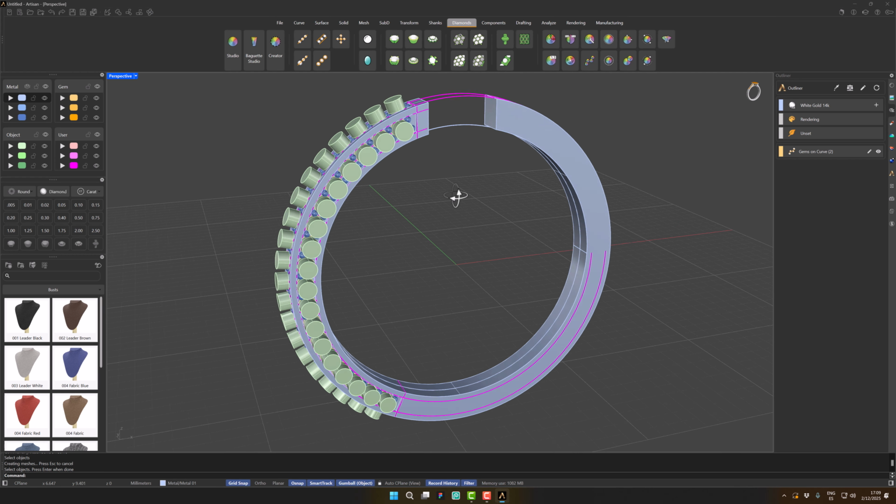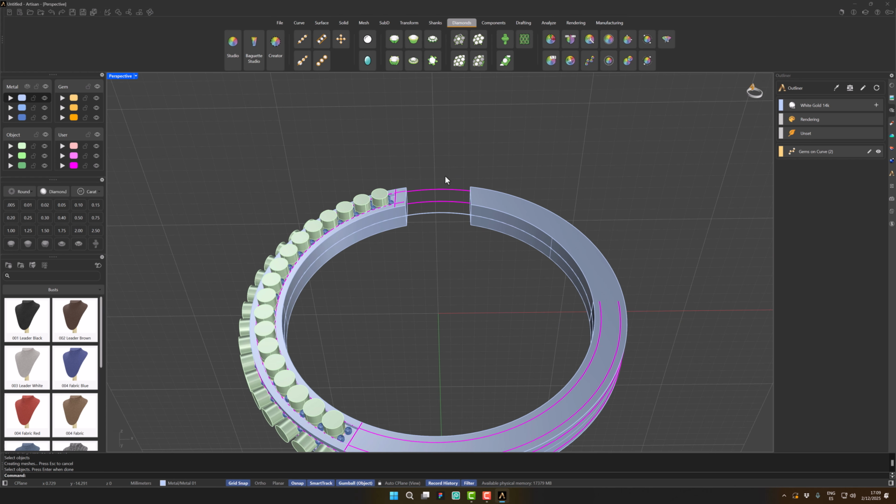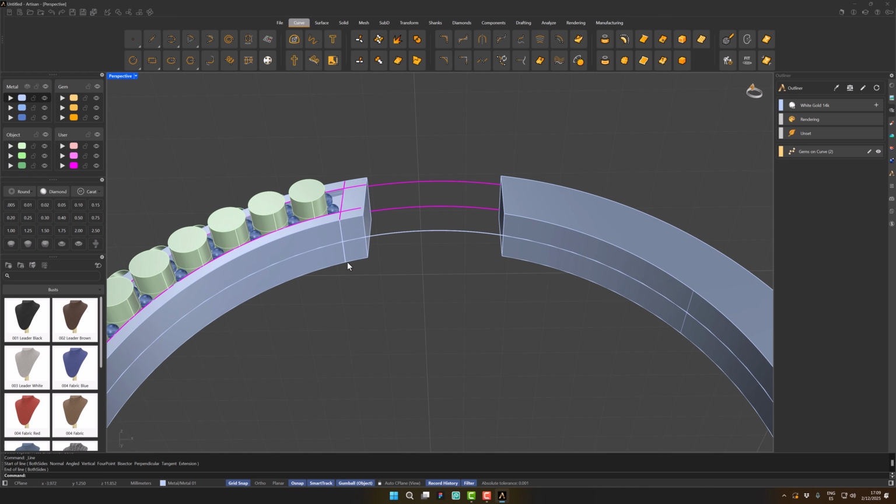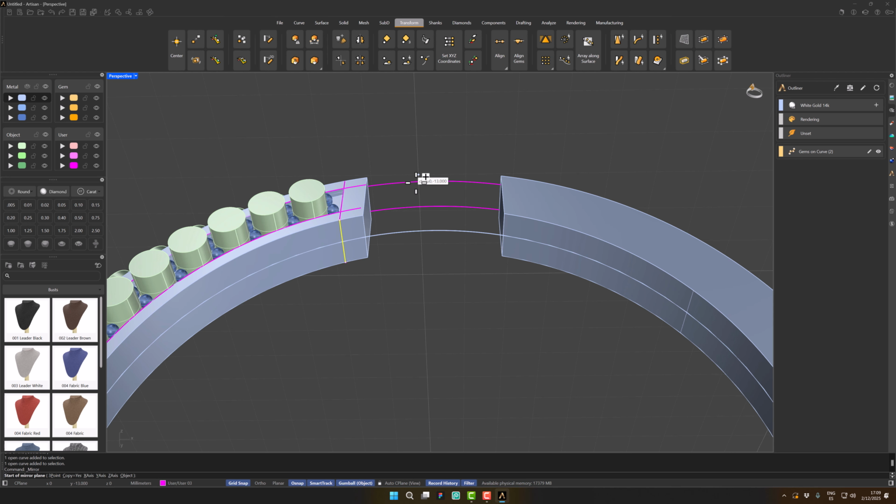Let's create the earring clasp arms. From the perspective view, draw a straight line at the upper opening. Use the mirror command to reflect it to the right side. Set 0 as the mirror center, and while holding Shift, click on the top to mirror the line. Hide the lower circle with the Hide command.